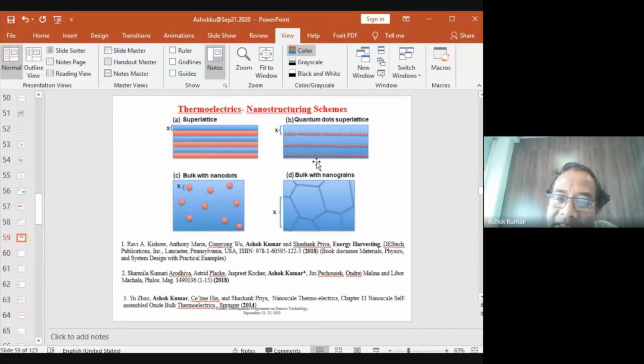We stated that electrical conductivity and thermal conductivity are both proportional, and you can violate that law using nanostructures. Here you can see bulk and nano, and these are the dots. So again, these dots work as a quantum dot for the phonon, not for the electron. If both electron and phonon enter this dot, the electron can pass and it will confine the phonon.